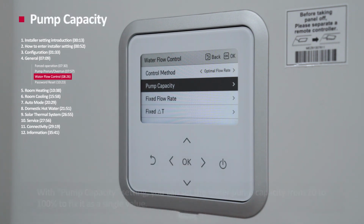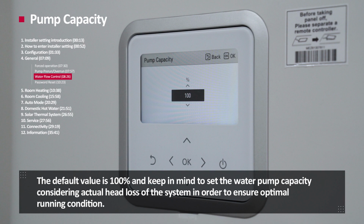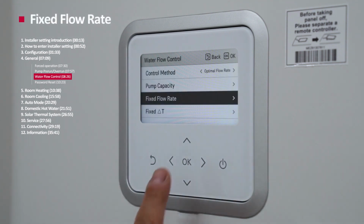Pump capacity. With pump capacity setting, you can set the water pump capacity from 10 to 100% to fix it as a single value. The default value is 100%. And keep in mind to set the water capacity considering actual head loss of the system in order to ensure optimal running condition. Fixed flow rate.